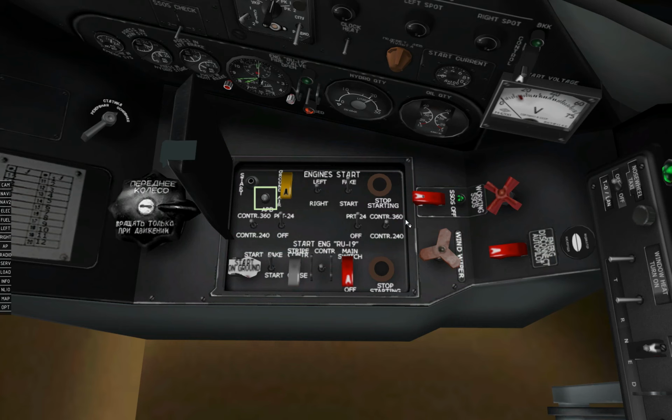start system annunciator, which indicates that an engine is starting, the engine start mode selector, which selects from two modes, ground start or air start, the engine selector, which is used to select which of the two engines you want to start, another mode selector where fake means cold spin or just a spinning of the turbine without actually starting the engine, as opposed to start, which means a real start of the engine. The engine start abort button in case start readings aren't normal or something goes wrong.